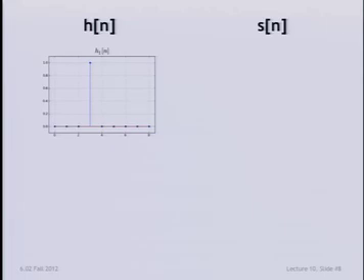And you see that the response actually happens subsequent to that input. So if the response starts at time 0 or later for an input that started at time 0 or later, then what you're looking at is a causal system here. Certainly in the case of a unit sample response. Okay, so what's the step response going to look like then?